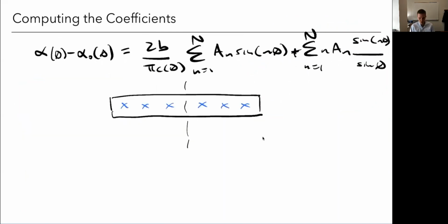I actually want to talk about a few other concepts that you might find useful here related to lifting line theory. So one is another way we could look at determining that the elliptic lift distribution is the minimum induced drag.